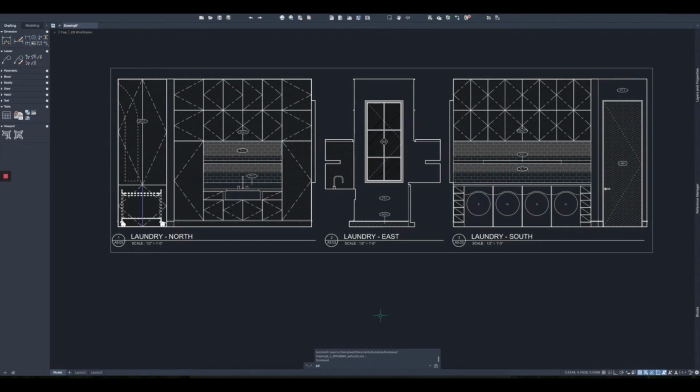We can do the PDF import command, which is just the word PDFIMPORT, all one word, and then hit enter, the space bar, right click, whatever, and it'll give you an option. You want to use the file option. That'll pop up your window. You'll be able to select your file. It'll begin importing. If the PDF is password protected for whatever reason, AutoCAD won't bring it in. You'll get an error. Otherwise, you'll get what you see here.